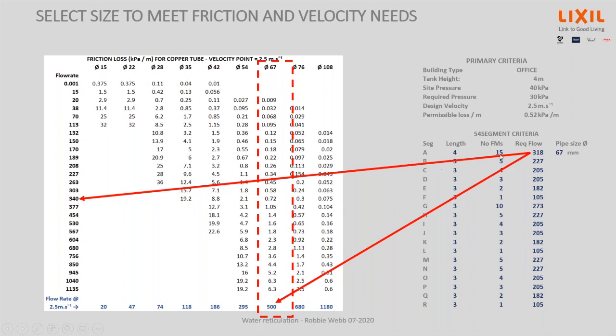And when you come back to the drawing, our outlet there is going to be a 67 pipe, okay? And on the branches, we're ending up with 54. And obviously, as we tee off to the standard FLUSHMASTER, we're going to go down to 3/4. Just for interest's sake, there is software which will analyze it much better, and you'll actually end up with more efficient sizing because it can look at the change per segment.